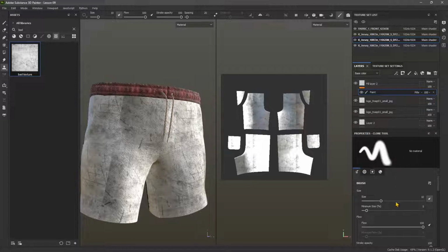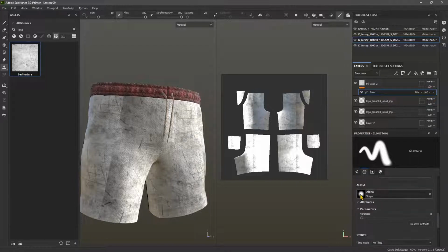Also make sure you don't have a pretty hard brush stroke. So here in the alpha, don't increase the hardness. You want to have a nice and smooth brush. So again, press V, press the left mouse button, and then start to paint on that other area. You can see that the little square on the other side is moving, which means it's getting those pixels as I move. And if I start again, for example, here, it's going to take that position again.